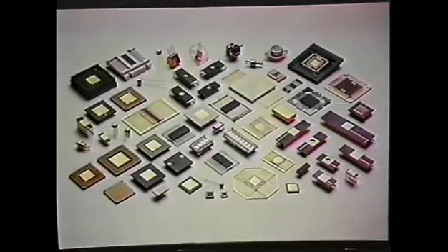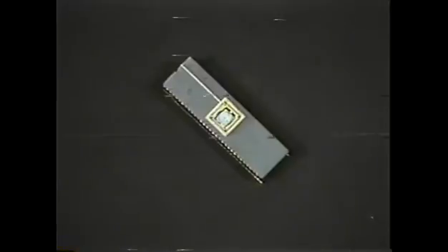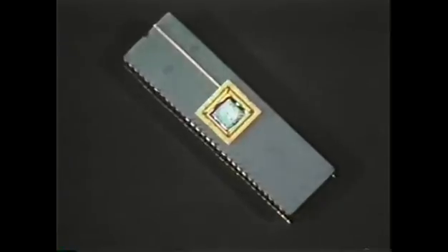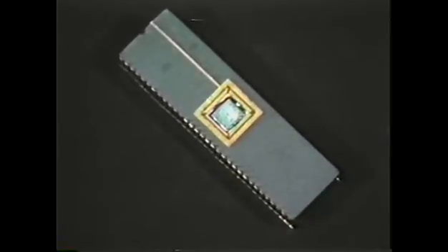Gross leak testing is a critical part in screening high reliability devices. Moisture from the air can penetrate into the cavity of a device through leak paths created by cracks and faulty seals. Once inside the cavity, the moisture can corrode the die surface or die pads and cause the device to fail in the field. Thus, it is very important to reject packages with these leak paths prior to shipment.